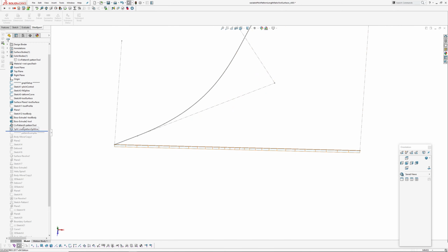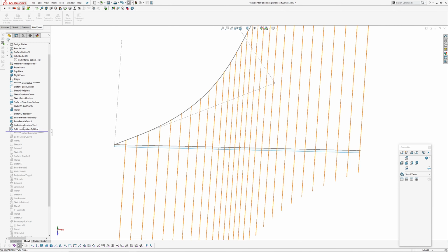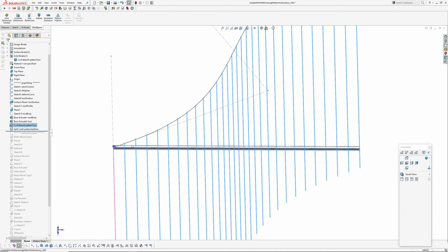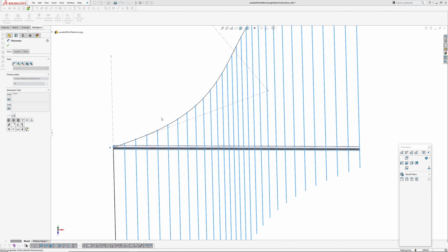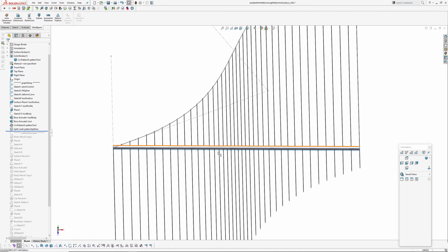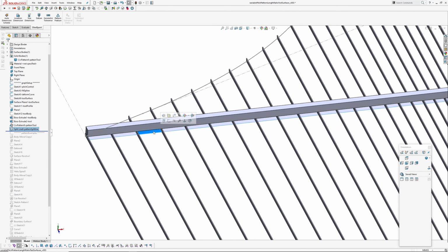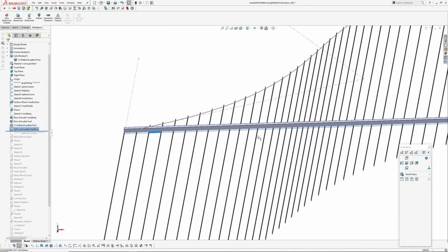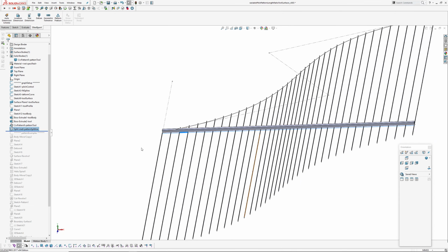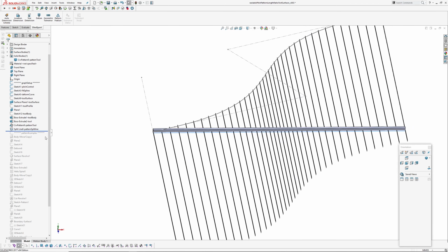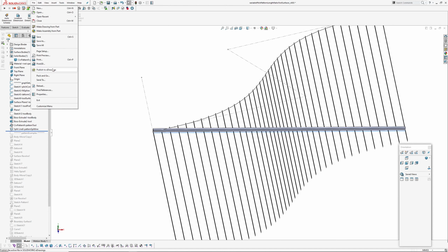Before I go into the examples, I'll just show you that because of the pattern, you can update the amount of instances, rebuild, and it all updates, and the split surface updates as well. So your pattern is captured on that tool ribbon surface. My examples will fall over because once you start applying this to things, you do need to keep the same amount of instances, otherwise you have to redo. Like I've got sketch patterns down here, so I'm just going to reload this file.